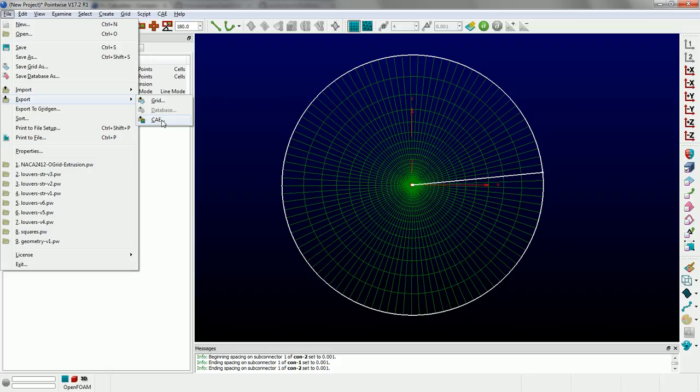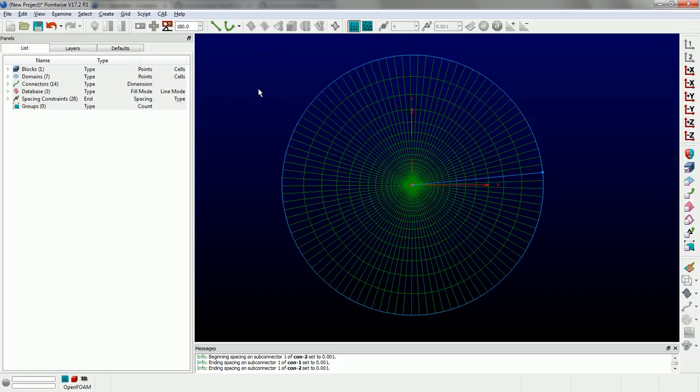Okay. So that's how you create an O-grid for an airfoil, appropriate for computing the coefficient of lift. You saw it was pretty easy, right? I mean, it's actually pretty easy, which means you could actually automate this, and it has been done.